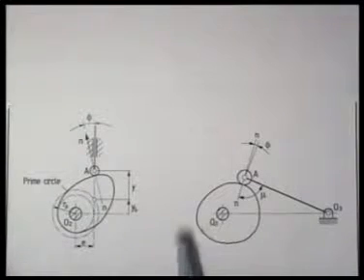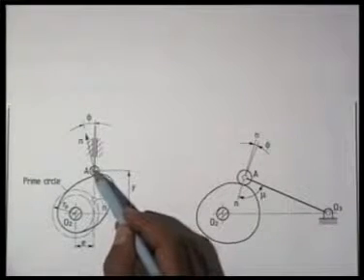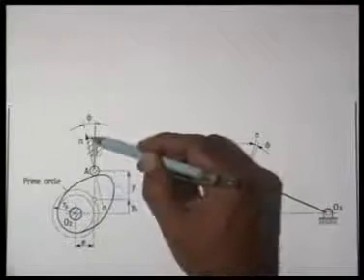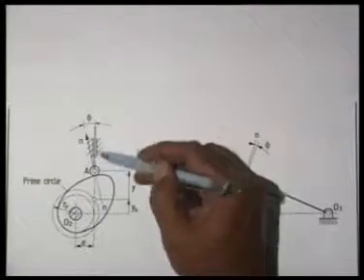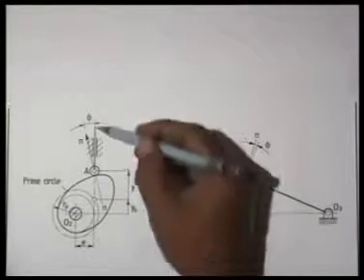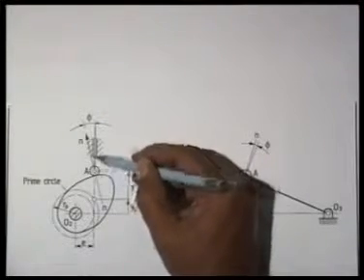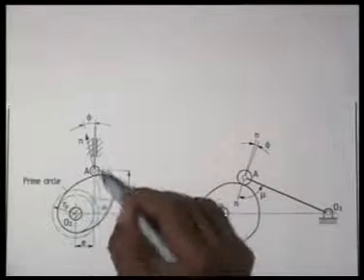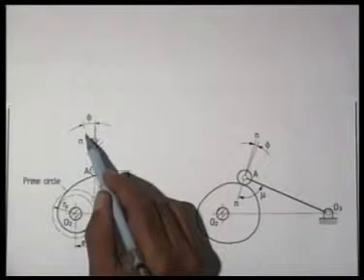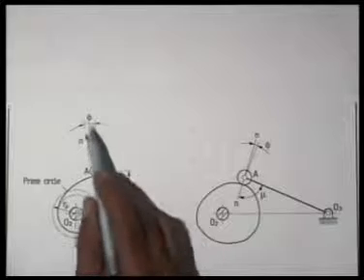In these two figures, we explain again the pressure angle. We have just now seen, if this is the roller follower and this is the cam profile, let this be the common normal, which passes obviously through the roller center. And this is the direction of the follower movement. But the contact force, if we neglect the friction force, then acts along this direction. And the angle between the direction of this force and the direction of the follower movement, this angle phi we call pressure angle.